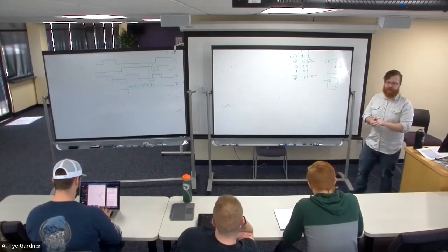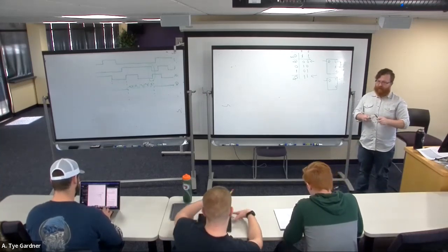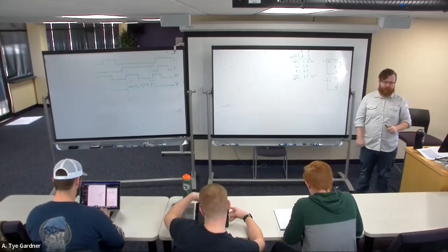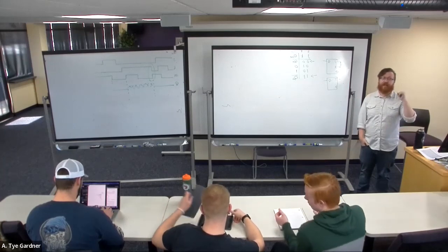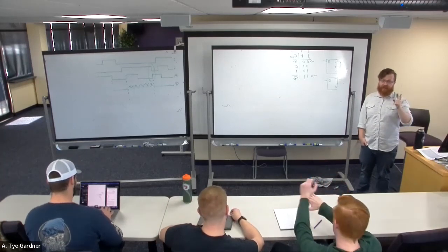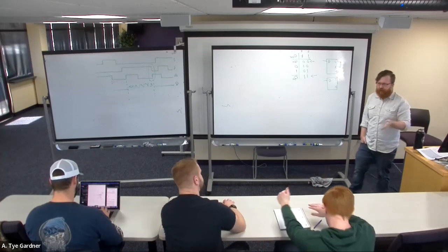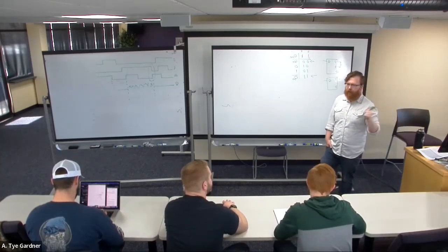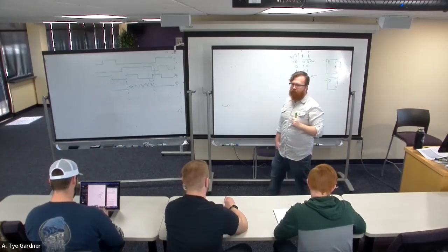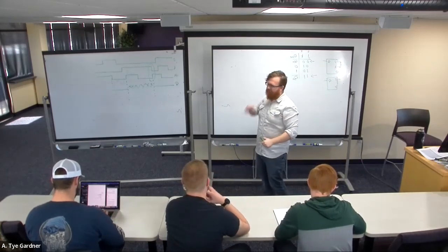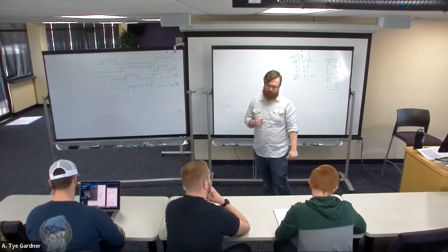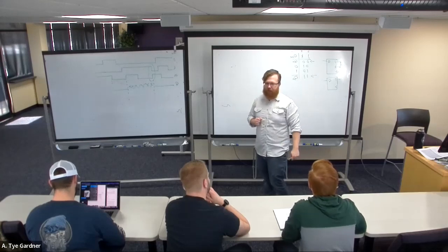Anyways, that's time so you guys can run away and do everything. I'll post the homework that's going to be mostly, I think, timing diagrams for flip-flops just to get latches and flip-flops, right? Latches react, they're combinational. Latches are essentially combinational devices because they respond immediately with a small delay to the changes of the input. Flip-flops are clocked. There will be a clock in the timing diagram when you do it. Look for whether it's rising or falling edge triggered. That's the bulk of the homework. You might have to write a little bit of VHDL for some of these modules.